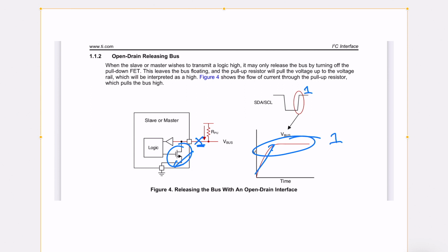So you can see here the bus originally starts out as a 1. Once the switch was engaged, it allowed current to ground, dropped the voltage to a logical low or 0 value, and then once it was done, it disabled the switch, keeping the voltage high and generating a logical 1 value.